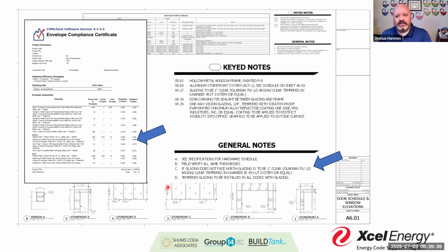1,000 pages of spec sheets when you could have put in the general notes that the glazing is going to be a 1-inch clear Solabond, tempered glass. If you'd put in U factor 3.3, I would have been done. But now I have to go back to the spec sheet and go through, is this 07280500, read 3 pages to get to the point where, again, you could have saved a couple seconds. And again, those can add up.